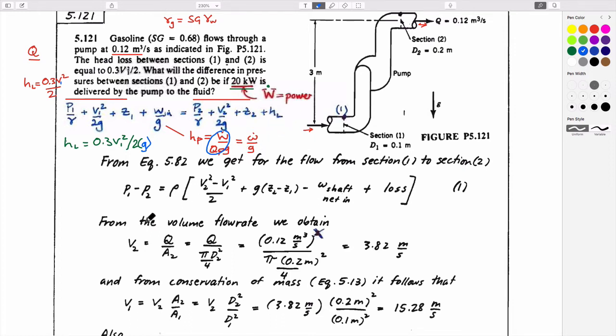So here, what's happened? I guess we've multiplied both sides of this whole term by rho G, because this term here all of a sudden loses this. So if we do that, we've lost the density. We have a density divided by gravity, so we have density here on the outside and just v squared over 2 because gravity's lost. And we need to take this G here, rho G Z on the outside, etc., and we've lost this. And so that's just the same expression written in a different way by multiplying through by density times gravity. We lose these different terms here.